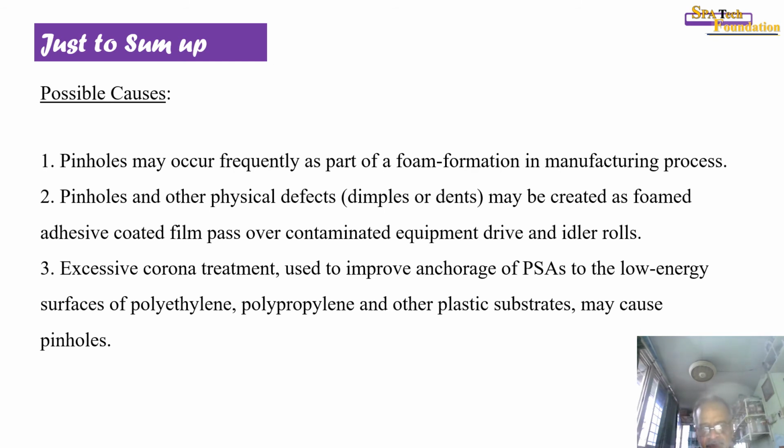Excessive corona treatment used to improve anchorage of PSA to the lower energy surface of polyethylene or polypropylene or other plastic substrate may cause pinholes. With excessive corona treatment, in this case, there are chances that the backside also gets some sort of treatment and